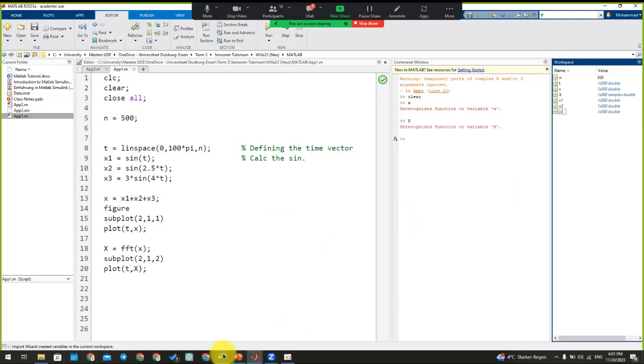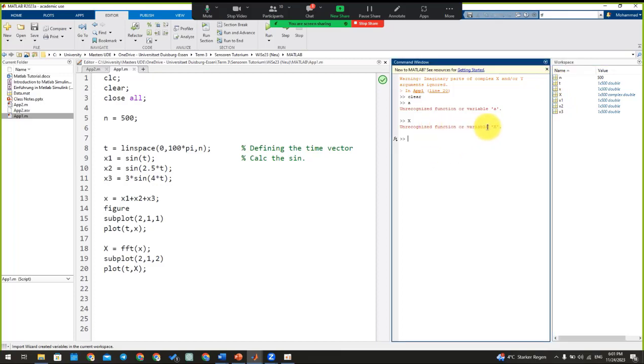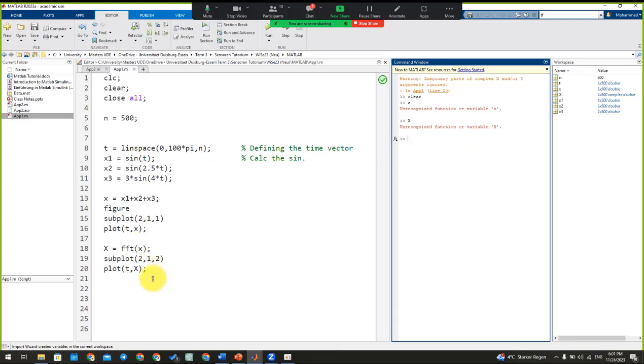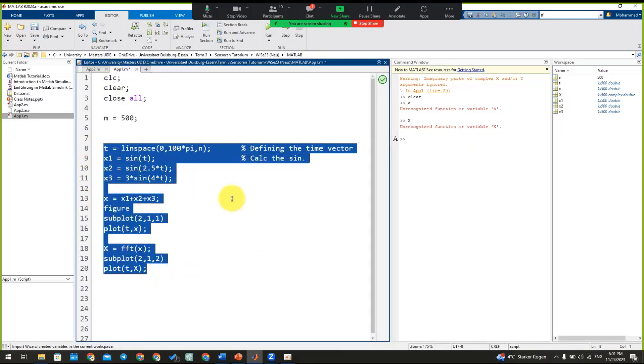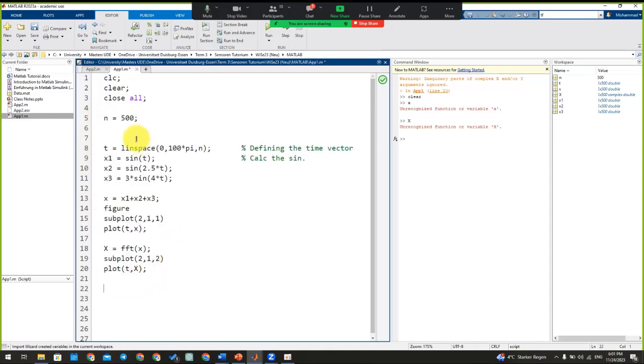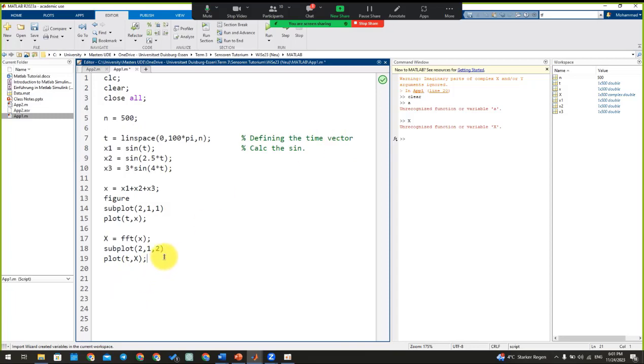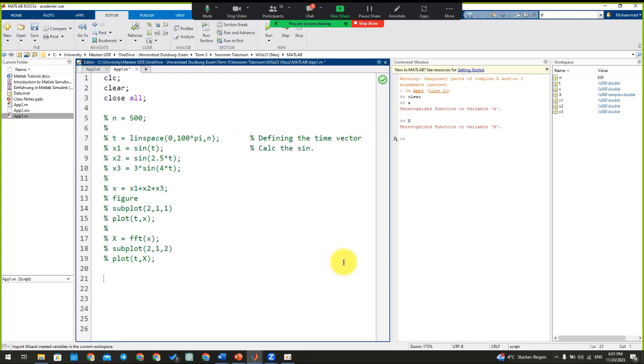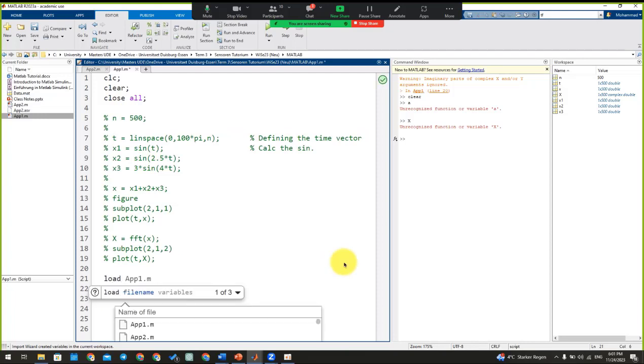So yes, as you can see here, these variables that we defined, calculated and saved in data.mat are once again listed here. And what that means is that instead of calculating the whole thing again, so imagine here are the first 20 rows which are really slowing the whole system, we can right click and comment them out, and from now on, since we calculated it just once, we can write here load, and then as you can see here, load data.mat.